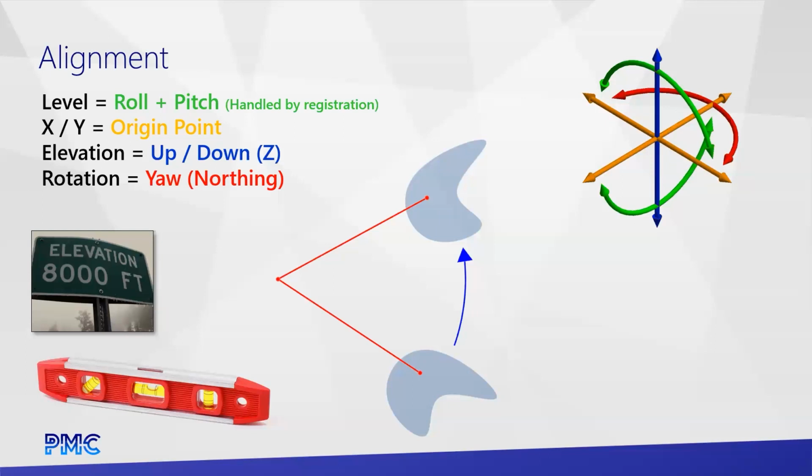Because in the real world, nothing matches what was designed in CAD. Your building grid will not match real life. Your building corners, even if you have the building traditionally surveyed, will not match because that data is much less accurate than scanning. And then elevation floors in real life are never flat. They're never even. So where do you want those points to be?